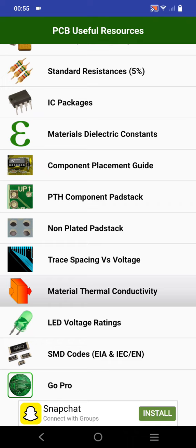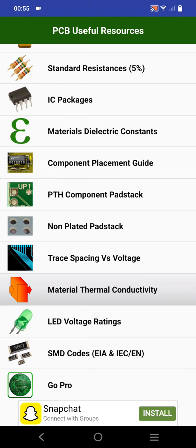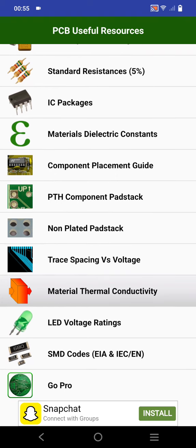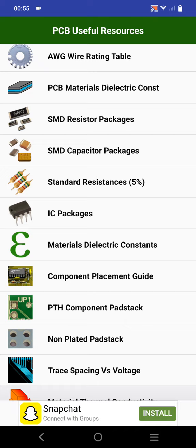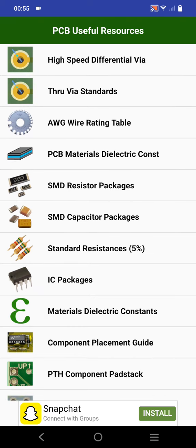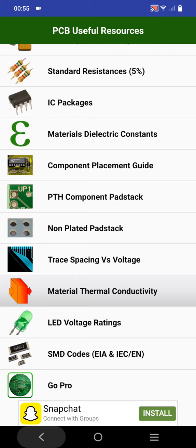You can have different kinds of ratings for this. A diode that is going to be used at 220 volts has its own ratings, so you have to get those kinds of diodes. You cannot use an ordinary diode on a high-voltage AC. Since you have to convert about 220 volts AC into 5 volts DC, you have to buy parts for that specific circuitry. You also have to decide what kind of resistors and capacitors to use. So if you want to see what a simple circuit will look like, we